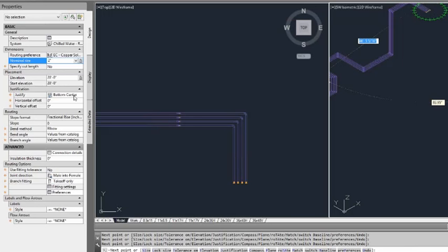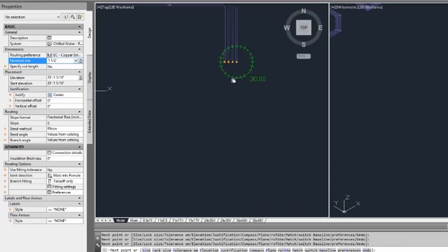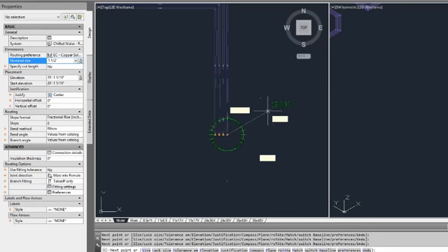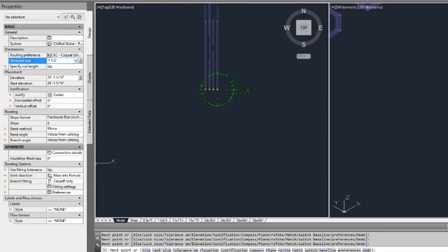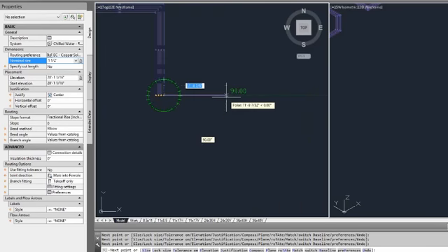So it's going to try to keep that bottom center, and the only way to do that is with an eccentric coupling. If I change this to just center center and then change this again, it's going to use the concentric coupling that I have set up in my routing preference. You can see that all 3 pipes change to 1.5 inches, which for the most part never happens in real life, but in the world of software, it can happen all at once like magic.